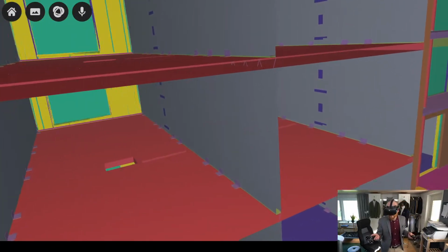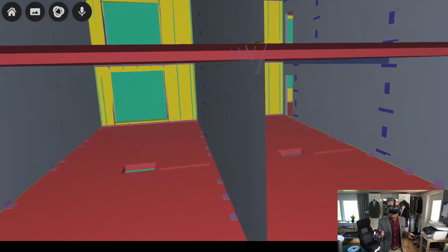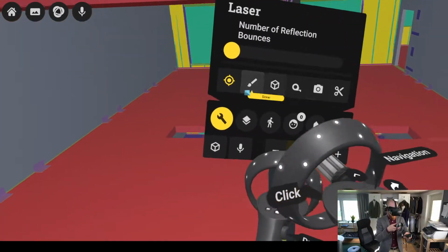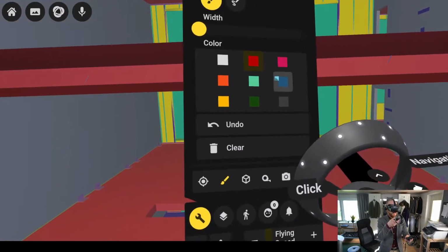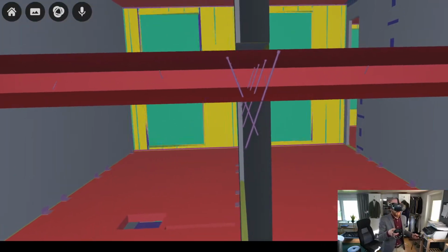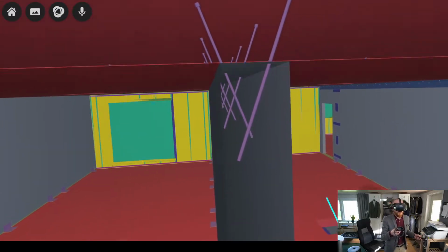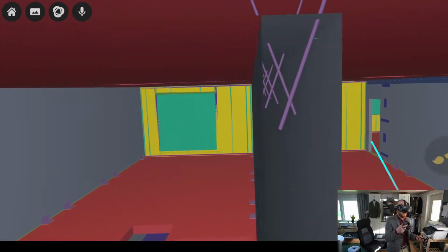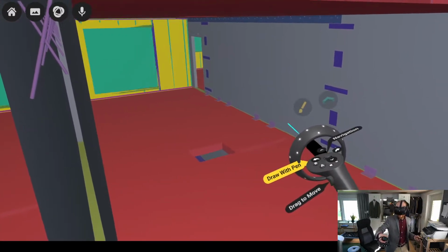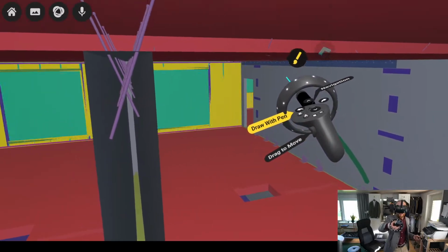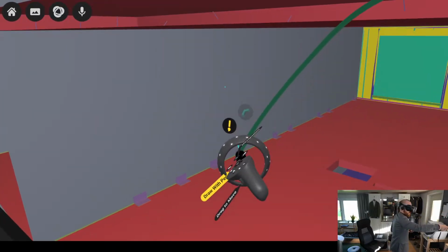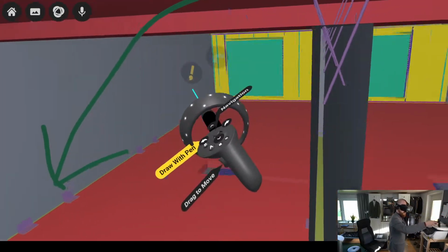However, the important thing here with regards to acoustics is that this is a sensitive flanking transmission path. And when you have a continuous CLT element between two apartments like this, that means that sound that is radiated in here can travel and excite this CLT plate, travel through the CLT plate, and then it's radiated here on the other side.